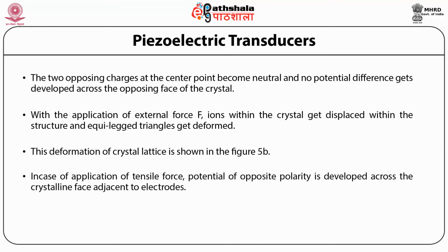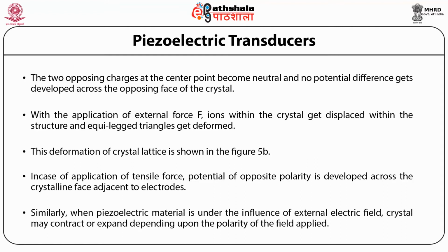In case of application of tensile force, potential of opposite polarity is developed across the crystalline face adjacent to electrodes. Similarly, when piezoelectric material is under the influence of external electric field, crystal may contract or expand depending upon the polarity of the field applied.